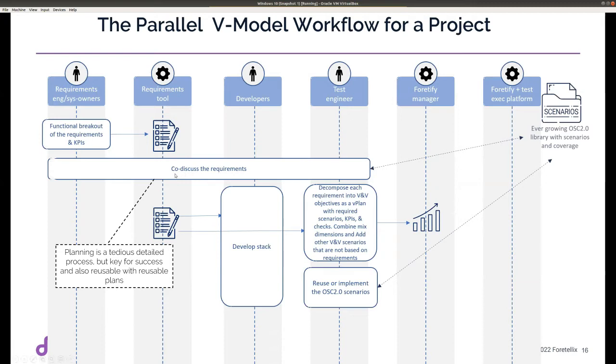Now, I want to say that sometimes you will just put a stick in the ground and say, okay, this is the coverage, these are the ranges, these are the values I care about, etc. And once you start the simulation, you will tune that because you'll see how things behave. You will see where the risk is. So it's okay to tune the requirements and tune the coverage once we actually see the execution and simulation going.